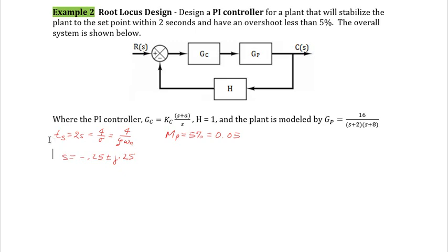In this case, we're starting with these 2 bits of information, the settling time and the overshoot, and we're going to use that to actually find this point. And again, in our case, we're calling it the point P, not the point S. So I'll remove that and we'll work through how we do that.